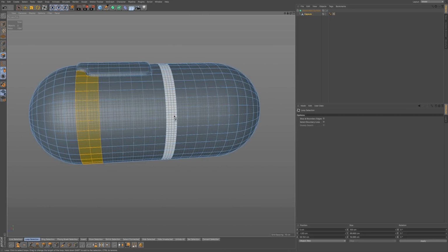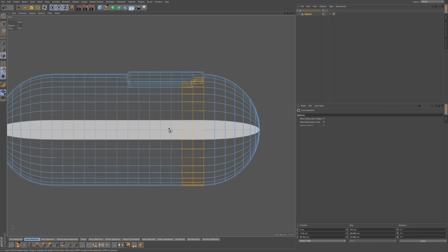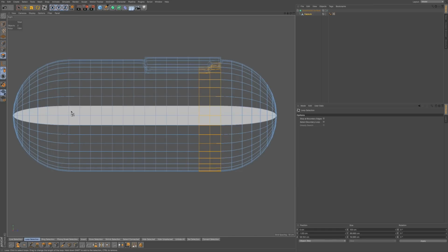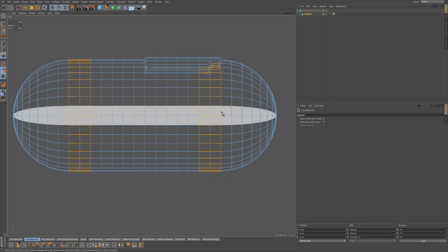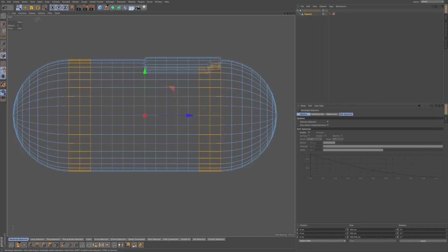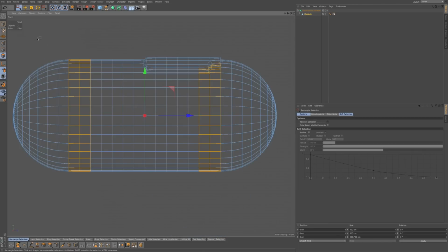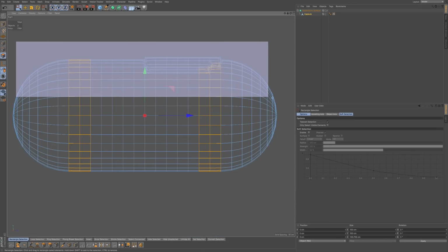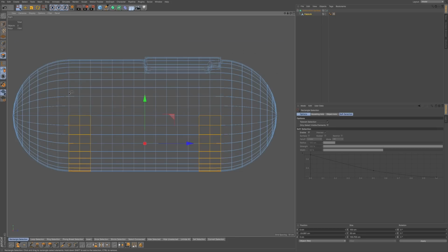And this might actually be useful if I go to the side, our side view. Let's put one here and here. So we selected these two loops. And what I want to do is go to my rectangle selection. Let's make sure we have tolerance selection checked. And I'm going to hold down Option. Oops, excuse me. Hold down Control. And let's deselect these ones at the top.